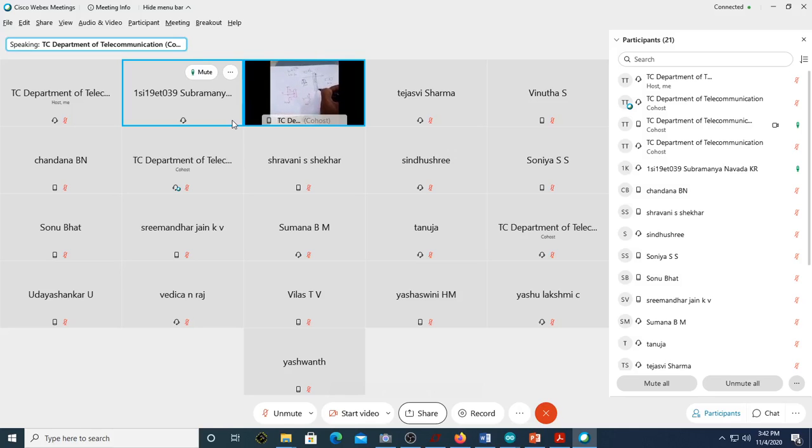Yes, sir. And whenever a person leaves this part of the door or this part of the path, he again presses this. When he presses this, does this become high? This will still be low because no person has entered here yet. Yes, sir. So when this is low-high, it means that person has left that particular zone. So does the door have to close now? Yes, sir. So since the door has to close, the motor which is connected to this door will move in the opposite direction. It will close. For how long? Again for 5 seconds. Yes, sir.